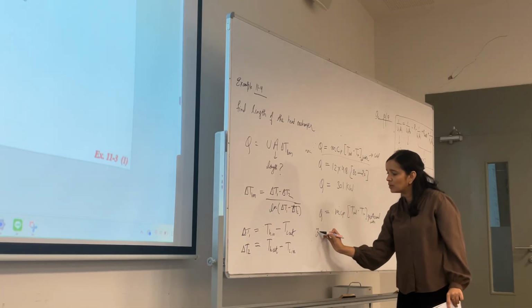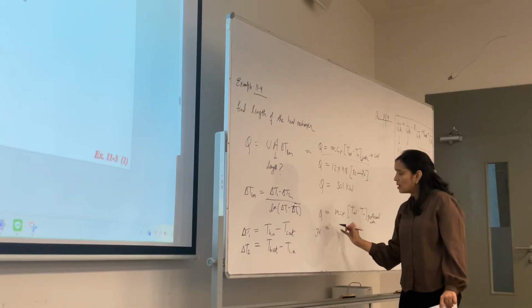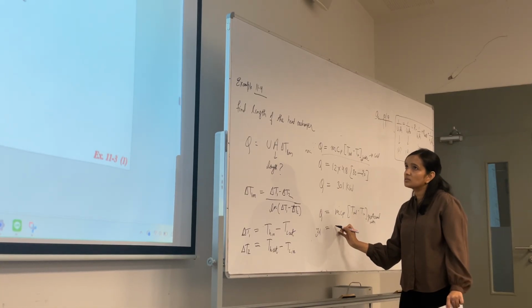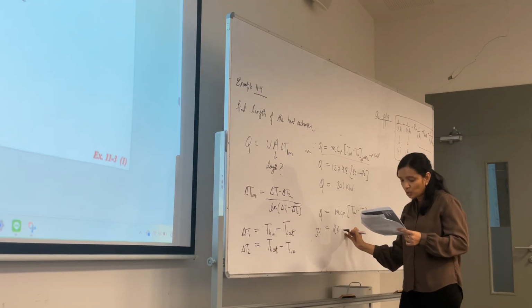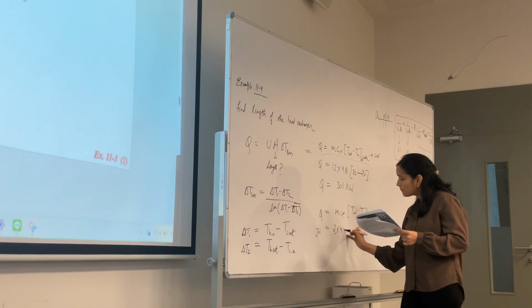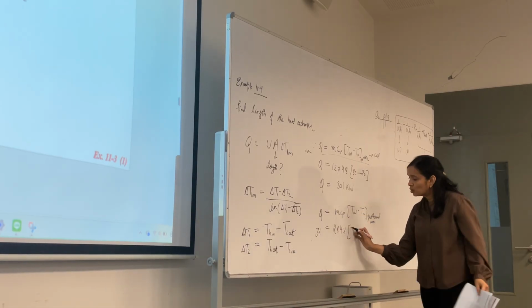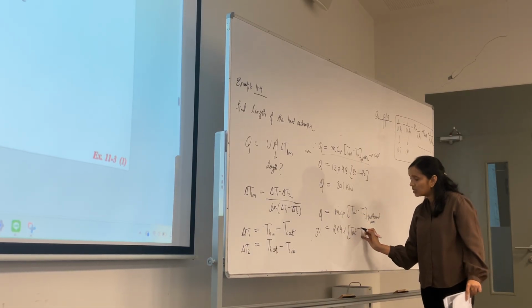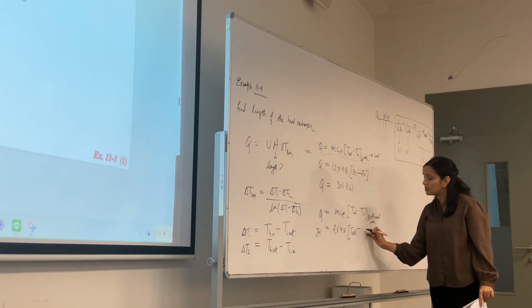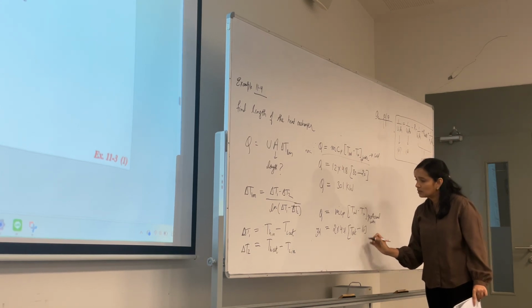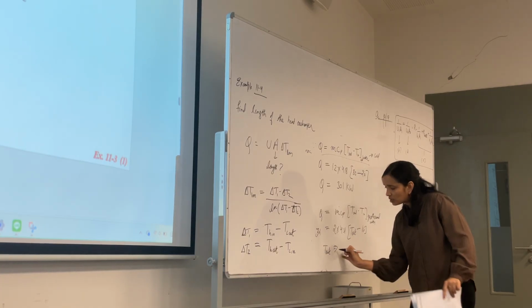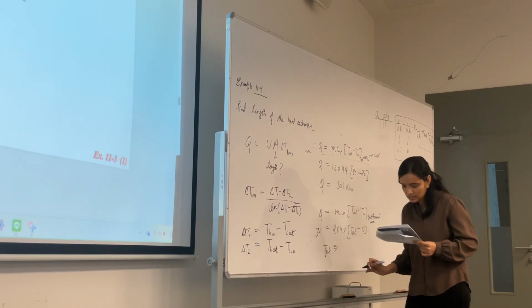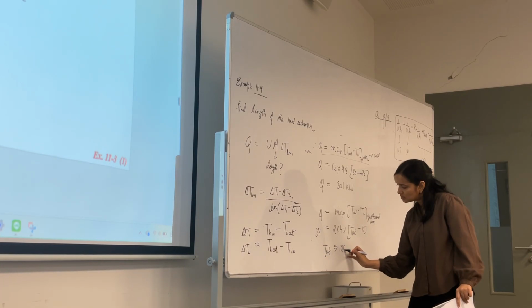So this is 301 for the geothermal water. Mass of geothermal water is 2 kg per second. Cp for the geothermal water, from the back of your book, is 4.31. We don't know T out, we are trying to find T out. T in of geothermal water is 160. From here you can calculate T out, so hot out is 125 degrees Celsius.